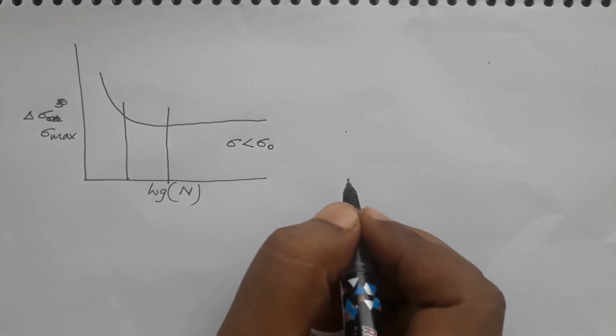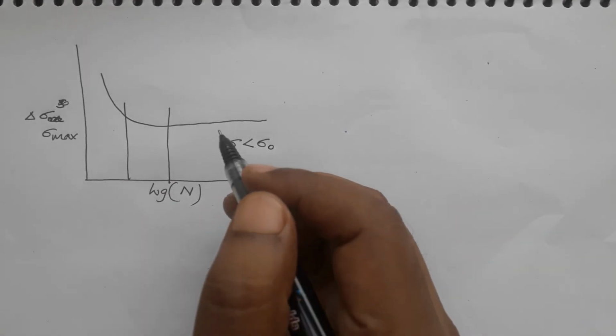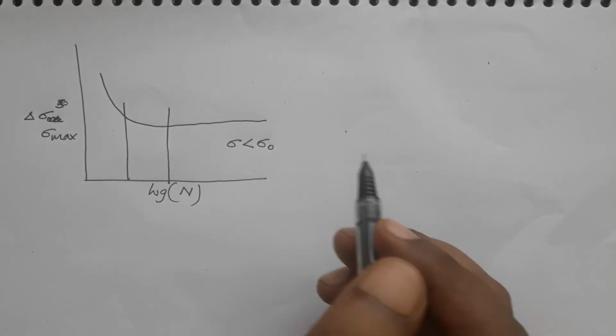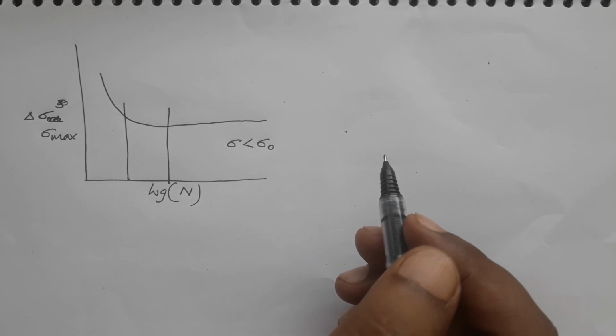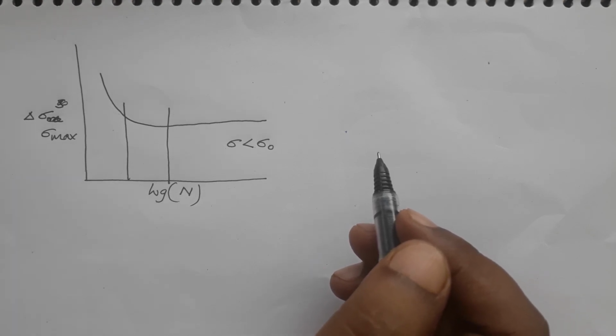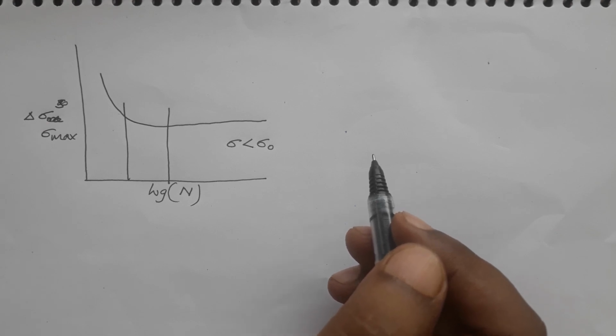So you only have elastic deformation, and people thought that material will not fail because the stresses are not beyond yield strength. So there is no reason for the material to get any damage and it should not fail then, but material kept on failing, and especially that happened in the cyclic loading condition.